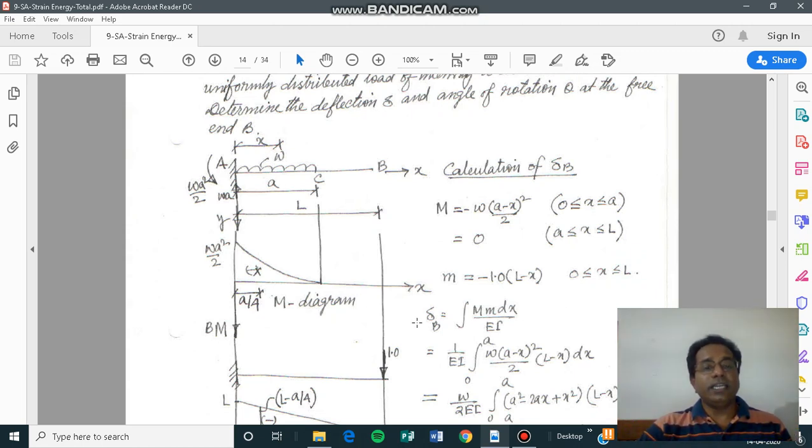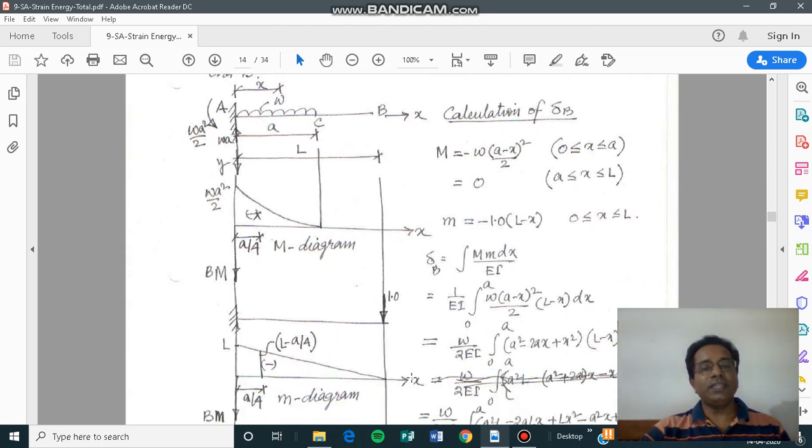Now, as we said, to get the vertical deflection at the free end, here the external load is removed and the fixed end condition is kept intact. We apply a vertical unit load here. Applying the vertical unit load, whatever section point I take, the bending moment is not going to change. So rather than giving two sections, I can calculate the bending moment in only one section. And the origin is this point only, and by considering this point as origin, we can calculate the bending moment at any point x.